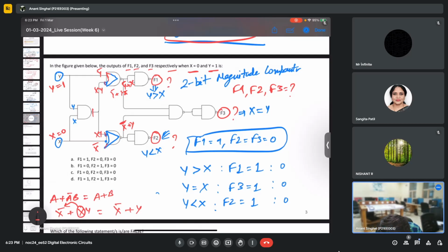NAND and then again a NAND. So two NANDs is basically a NOT gate. If I do the NAND of this thing, the NOT is completely cancelled, and F3 is just the multiplication of these two things. So I'm doing that. So this will be x, y, sorry.